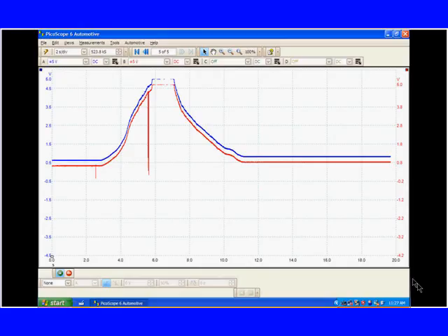Here is one we've got to really spend time talking about. Now this was a problem we located only with a lab scope. There were no codes. The car had a momentary lag in power, then picked up again afterwards on an acceleration. And it comes in at different points at different times. What happened here is as the dual processors computed the two values, at the one point we had the big glitch. The red and the blue did not agree.